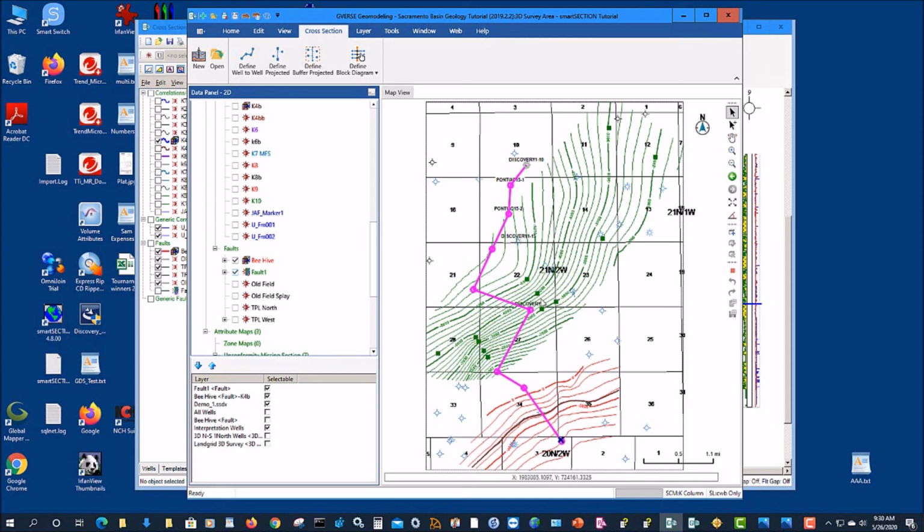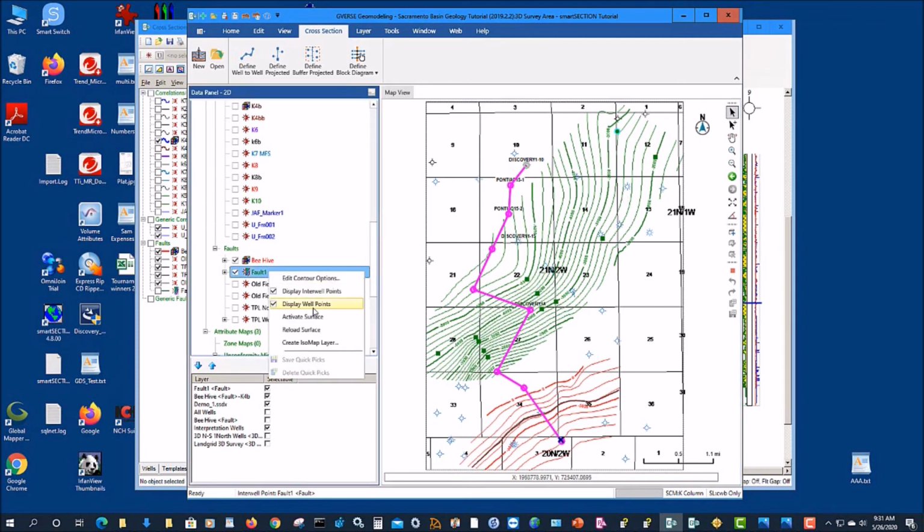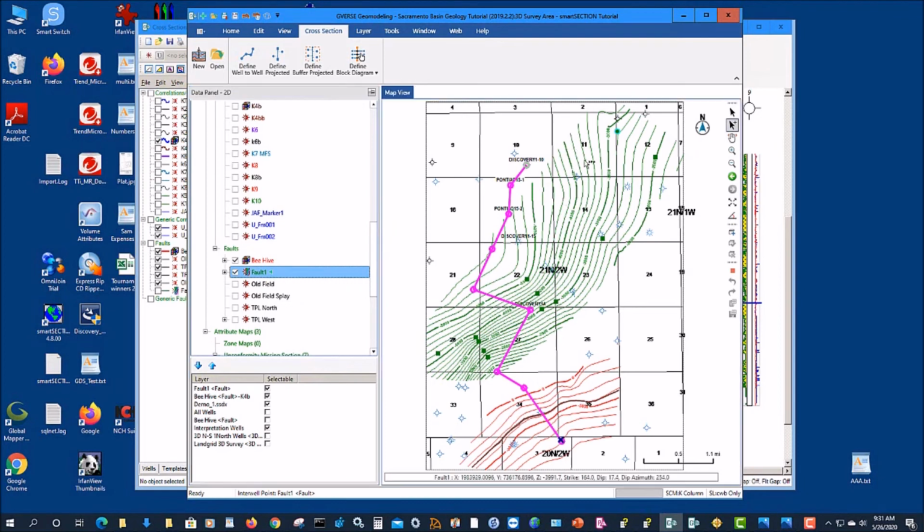They're not on wells. They're picked in interwell space, and they can be adjusted if you feel like you need to tweak your fault. And because I have sourced from Wellbase and it's recalculating the fault, and you've got fault offset, so it's going to be remodeling, if you will. Because we sourced from both, and this is the trick, guys, because we sourced from both the data points on the IsoMap layer and Wellbase, we can in fact come in here. Let me make sure that my fault 1 is the active surface. There we go. We can in fact pick additional interwell points to configure this fault beyond control.